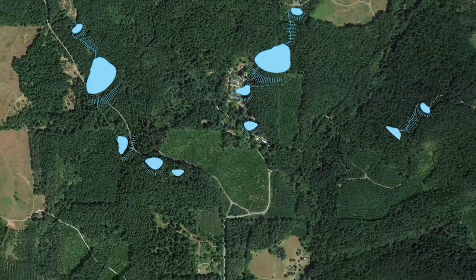Now that cross-sectional diagram can also illustrate the location of the clay that actually maintains a permanent seal on the dam and the bottom of the pond. When we look at a cross-section, we can see that there's really three ways to build the dam as far as the content of the soil type. The first and the best way to build the dam is to put in a key.